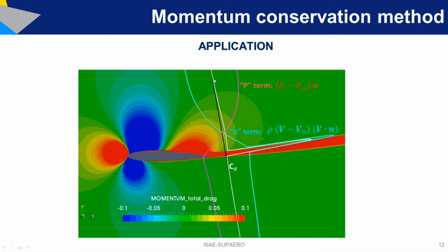So before tackling the particularities of all this, basically the major objective of applying this formulation point by point all along the survey line is that this will allow me to determine the local drag density at each point, and ultimately, by integrating data on this infinite plane, it will allow me to determine the total drag. That's the major objective of this method, to compute total drag based only on the information available at this black survey plane. That's all. Now, let's tackle the particularities of this method.